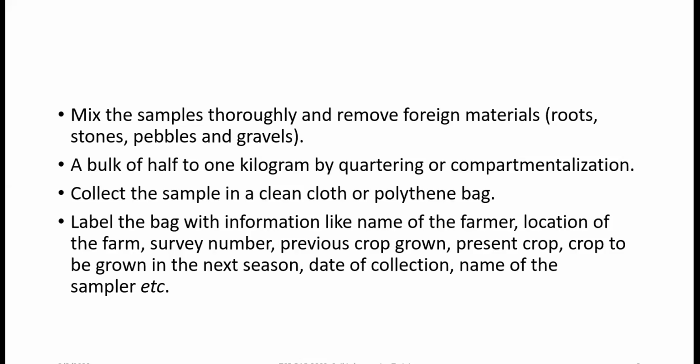So you are always taking grams from the soil. So when you are in the field, take the appropriate weight of soil, so that you do not end up, when you want to do a certain measurement, without soil. You have to take an adequate quantity of soil during sampling. But in general, 0.5 to 1 kilogram is quite enough for most measurements.